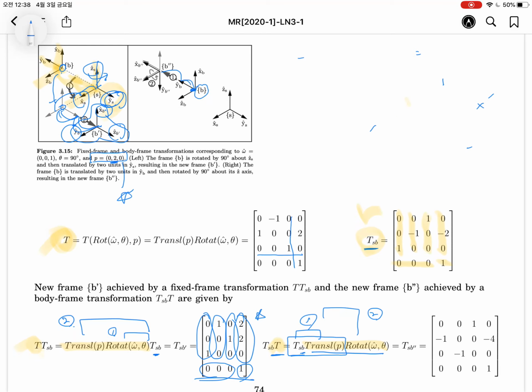So this frame is going forward 2 units, and then we have the new body frame here. Okay, the orientation is aligned with the B frame, and then we will take the orientation in the Z direction. Here, the Z direction is like here, and then we take the 90-degree orientation. So the x-axis will be rotated here, and the y-axis will be rotated to here.